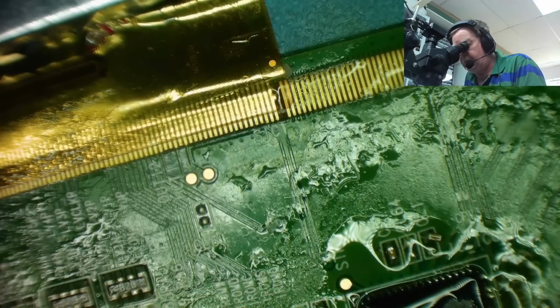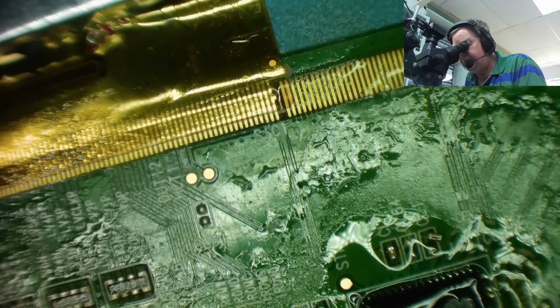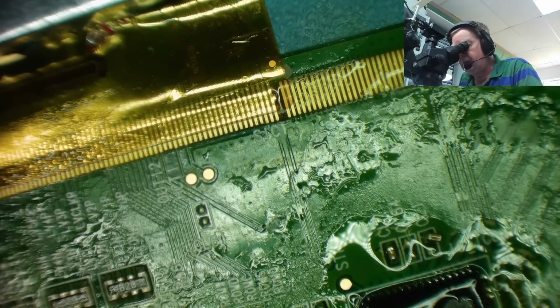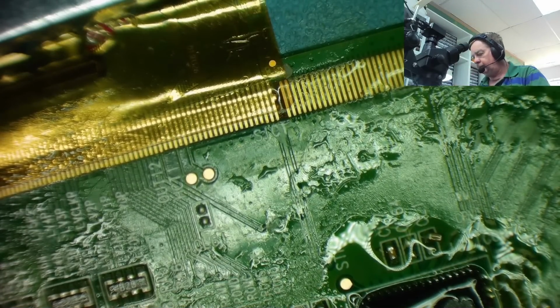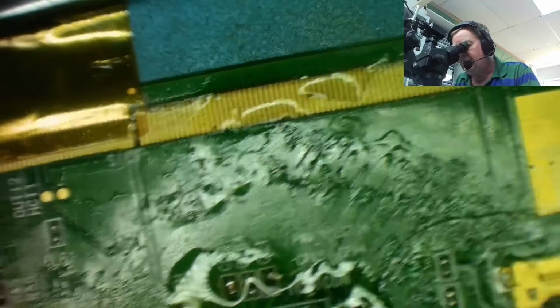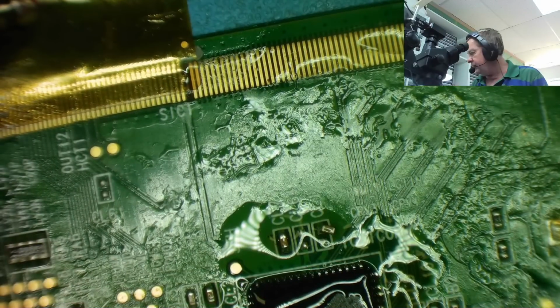As you've probably seen a lot of these videos now, I'm using this large tip because I can get a lot of heat into the joint. With a small fine tip you wouldn't do it. Okay. That looks not bad actually. Let's clean up the stuff off that, the flux.